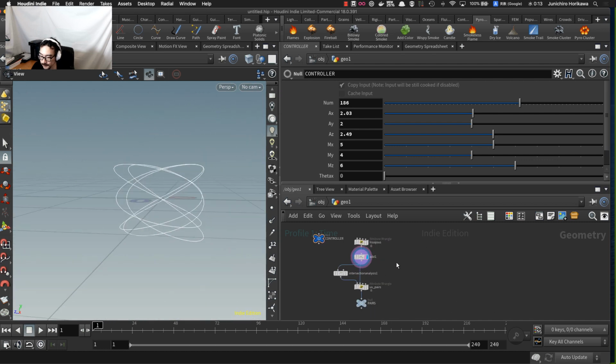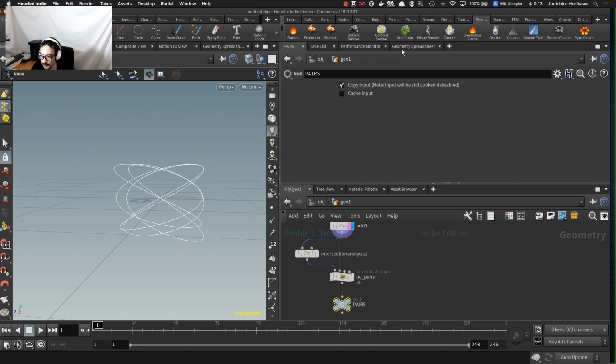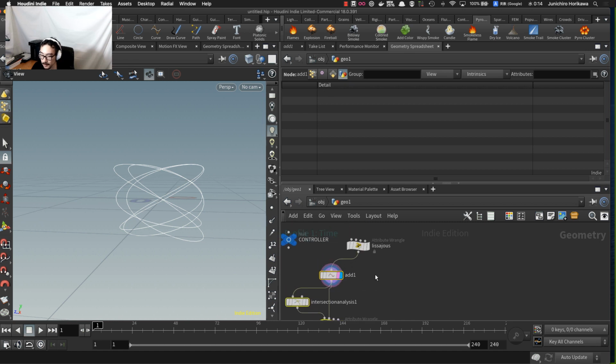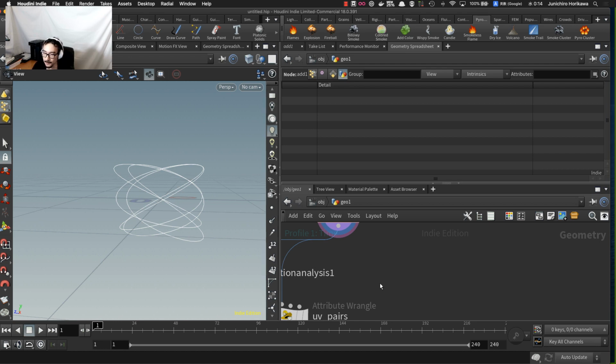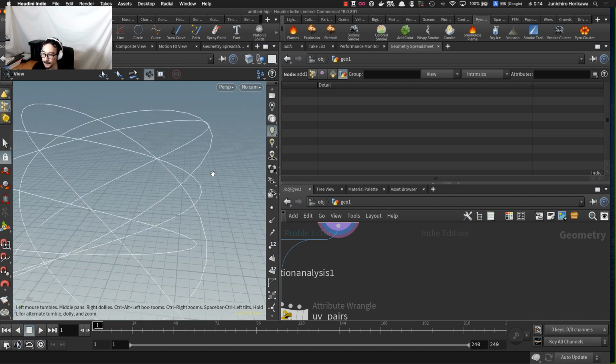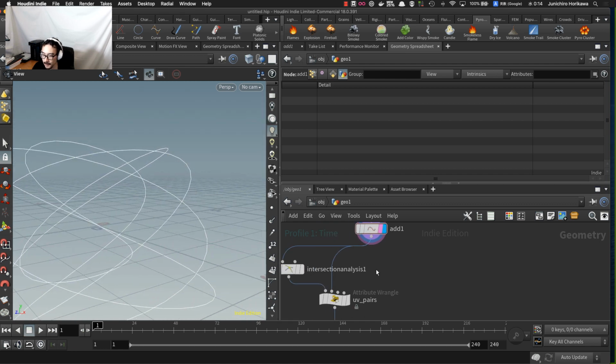Alright, now let's create a for loop in order to create a bone structure on top of this curve using this segmented curve information. Okay, gonna bring this up to the left side. And first, in order to create a rotational bone structure, I need some information on top of this curve, which is the frame orientation, the normal direction and the up direction for each point on this curve without much of a twist.